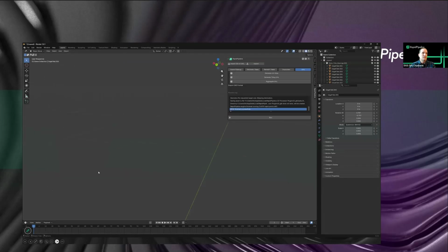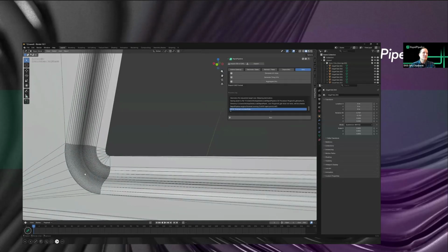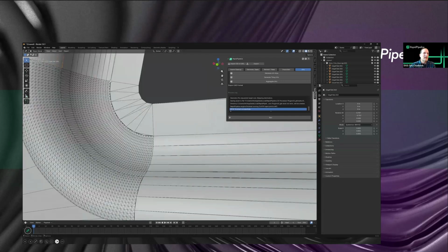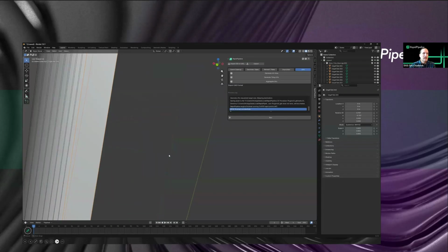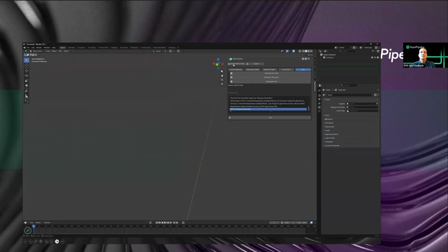So you don't end up with these really strange differences in resolution, which make it hard to work with these things because they're really different, and you'll get little gaps in between things. So if we zoom in tight there, we'll see that this thing only has these really long, thin faces. And there are actually gaps between this surface and this because they're not matching up in their vertices. So let's re-import that and we'll turn on those options we talked about and see how that works.